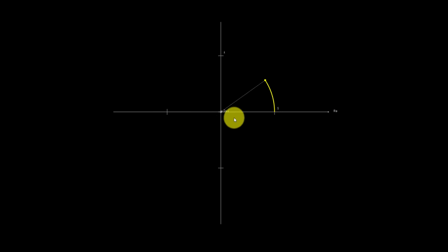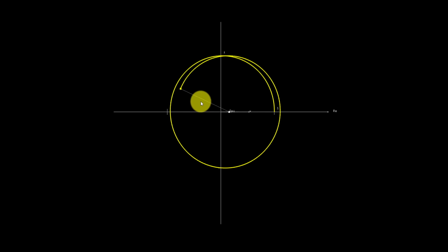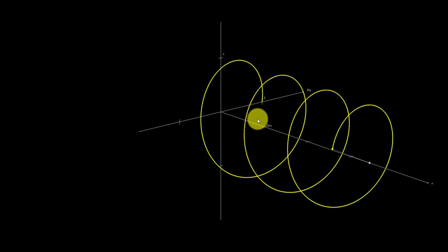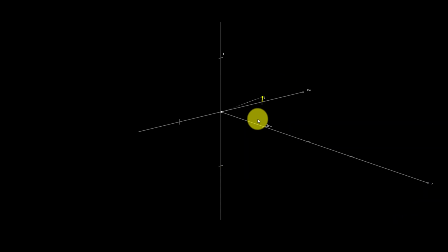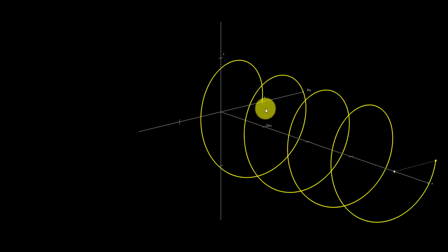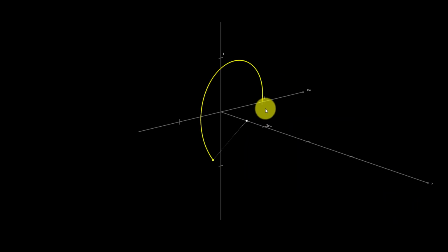So this thing has e to the power j omega t written right next to it. If I just rotate this figure, it looks like a counterclockwise rotating spiral. And in another part of this video series, I will be explaining that if the phasor is rotating in the anti-clockwise or counterclockwise direction with respect to time, we call it a positive frequency phasor. If the phasor had been rotating in the clockwise direction, we would call it a negative frequency phasor. I'm going to explain why we need positive and negative frequencies to represent a real signal, but that's a topic for another video.